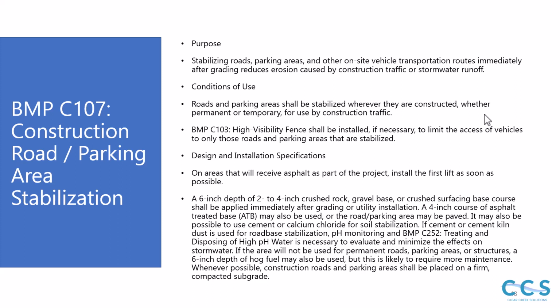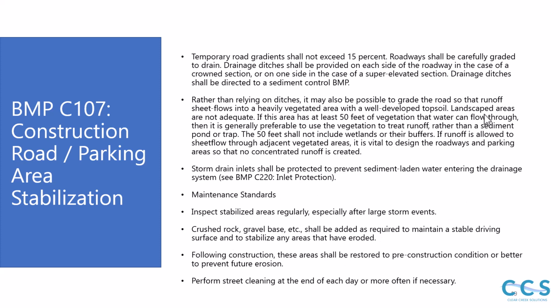Whenever possible, construction roads and parking areas shall be placed on a firm, compacted subgrade. Temporary road grading shall not exceed 15%, and roadways shall be carefully graded to drain. Drainage ditches shall be provided on each side of the roadway in case of a crown section, or on one side in case of a super elevated section. Drainage ditches shall be directed to a sediment control BMP.